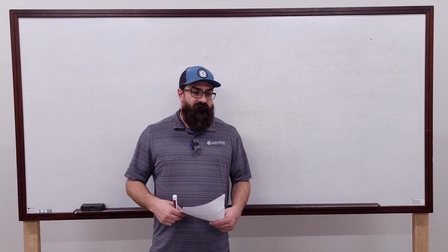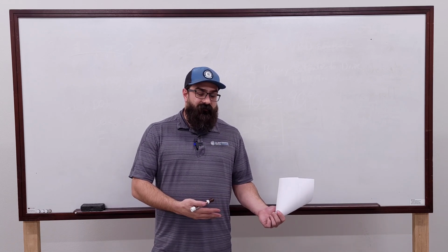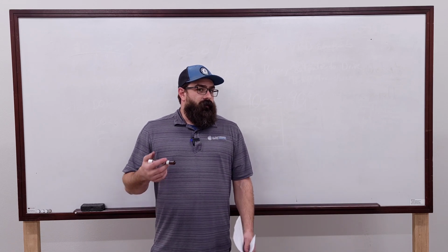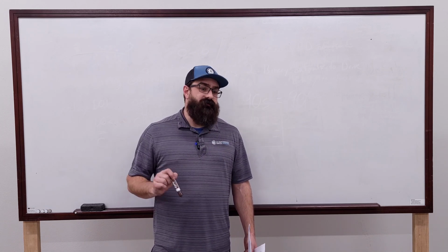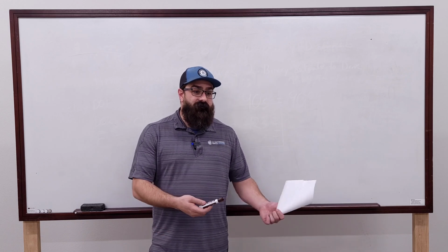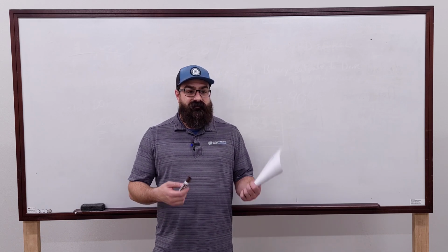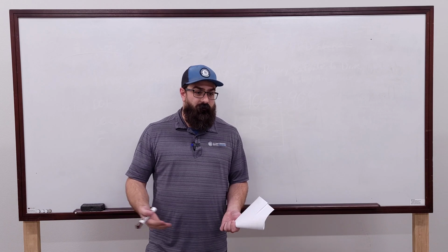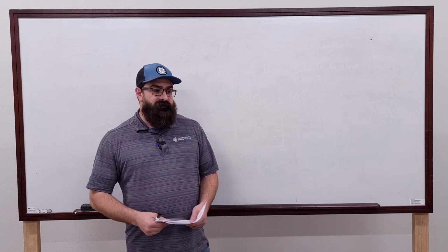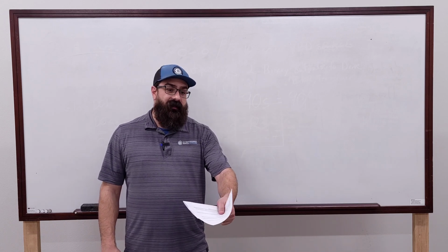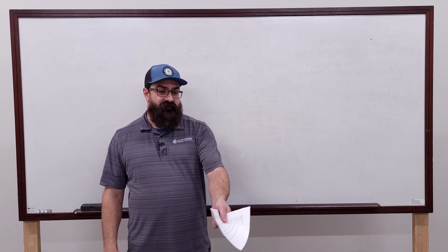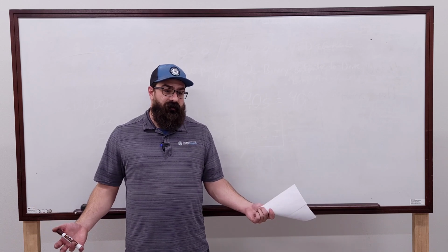Yeah. Everything else. If everything's right and you're still not getting the right answer on the controller, the only other thing that it can be, if it's not the input, is how the controller's configured, right? Like it's set up for the wrong sensor, or it's set up for a different sensor. You know, it may be that it's a Honeywell controller that's set up for a 20K sensor. Well, somebody had a spare 10K laying around, didn't know it was a 10K, and they just stuck it in there, and now it's reading all kinds of crazy.